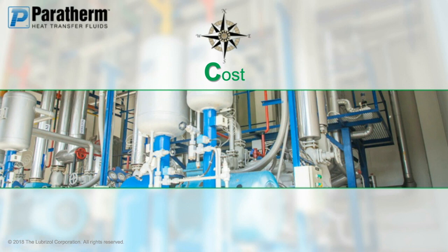The rate of replacement. If you're at that extreme operating temperature range, if your fluid that you're looking at is limited to 600, but your process calls for 590, rest assured that you're going to be replacing that fluid more commonly than not. So rate of replacement is something really key to put into the analysis. The upfront capital investment of putting in the aromatic fluid is 3 to 4 times the cost. Well, if the life cycle of that is expected to last 5 or 6 times the life of the mineral oil, that's going to be something that you can really consider.